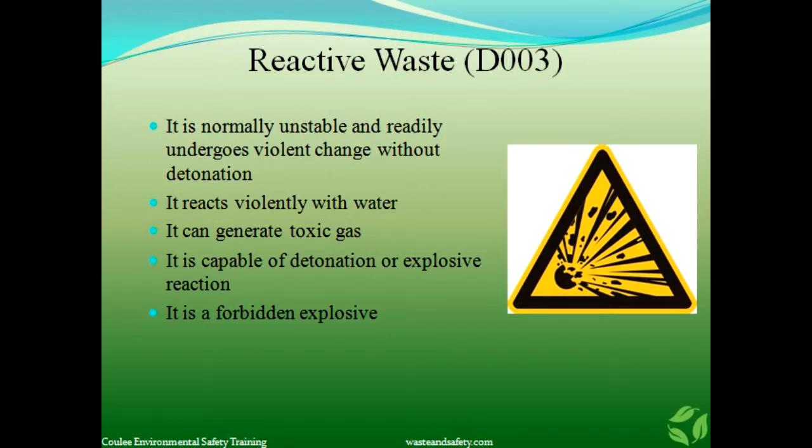It could be a cyanide or sulfide-bearing waste, which when exposed to pH conditions that are between 2 and 12.5, can generate toxic gases, vapors, or fumes in quantities sufficient to present a danger to human health or the environment. It is capable of detonation or explosive reaction if it is subject to a strong initiating source or if it's heated under confinement or in pressure. It is readily capable of detonation or explosive decomposition or reaction at standard temperatures and pressure. Or it is a forbidden explosive as defined in the DOT regulations, or it could be a division 1.1, 1.2, 1.3, or 1.5 material, again as classified in the DOT regulations. Any material that has any one of those properties would be considered reactive.